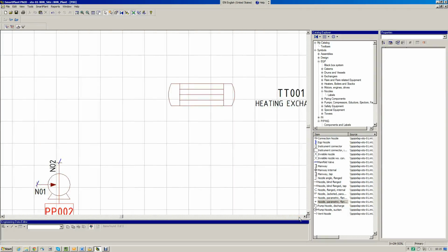We continue to the heat exchanger. We need a nozzle on the tube side here, and it's a double pass, so it goes up out there. We will have some cooling of this media. Cooling water coming in there, and here you can now see that it would be better to have that label on the other side.